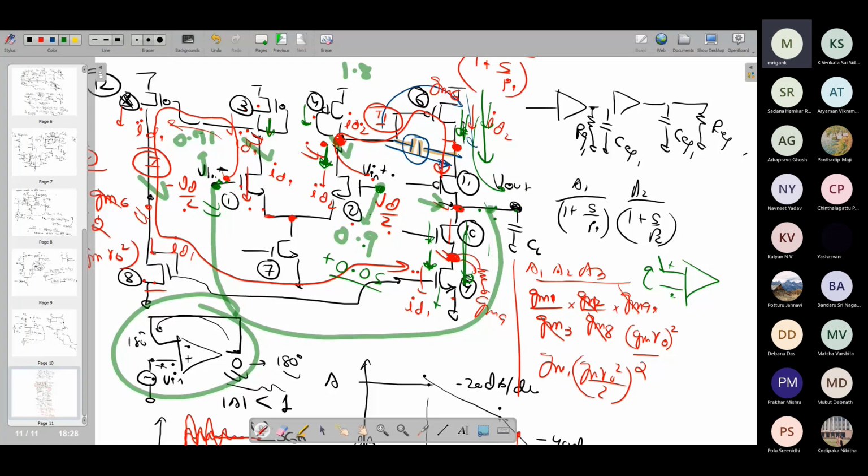So in the single stage amplifier, when we study common source, we don't have this facility. We don't have any feedback, any DC feedback. Here we have that, and therefore we can operate it with the help of this DC feedback. We don't need to worry about the output DC bias. Even if you put another stage, say a common drain, and take the feedback from here, feedback will still ensure that the output of the common drain and the input DC are at the same point, and that will ensure that a particular DC potential is achieved at the output of the first stage.